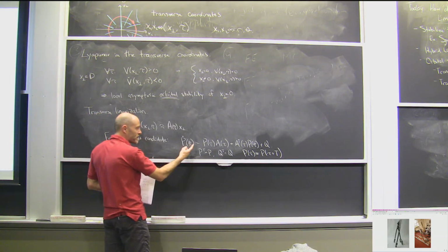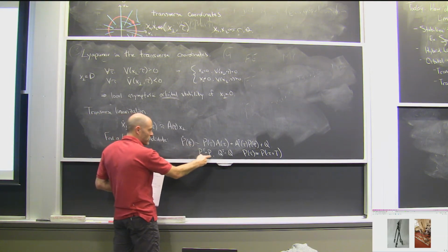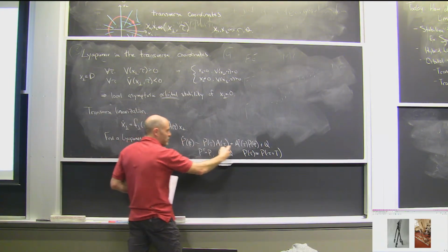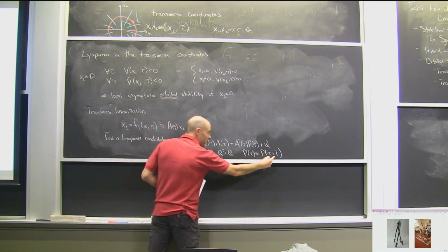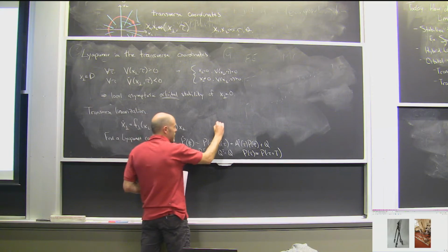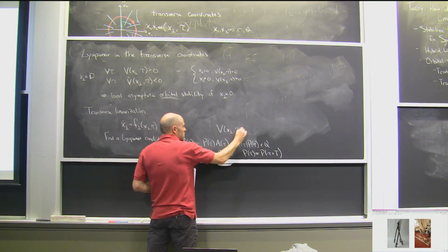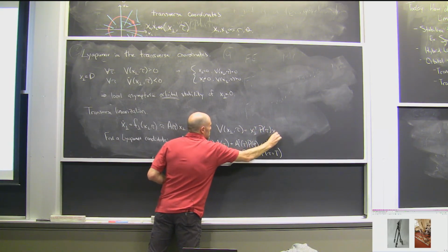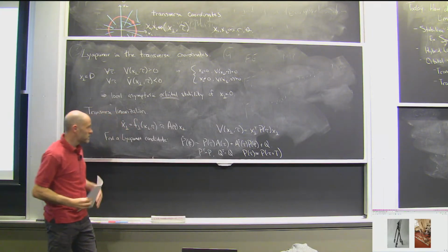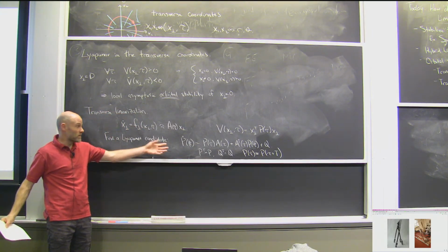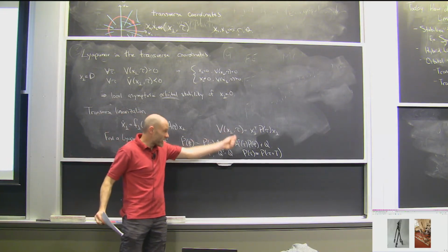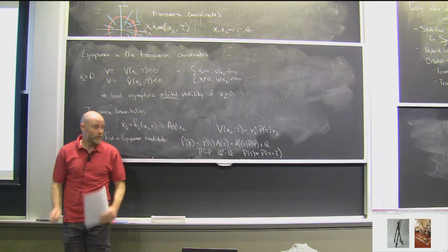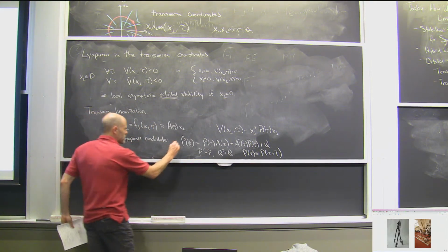So if I can find a symmetric positive definite matrix that's a solution to this Lyapunov differential equation, a periodic solution, then that gives me a Lyapunov candidate like this. That's a mechanistic way to come up with an initial quadratic Lyapunov candidate. Yes? Shouldn't this be negative P dot? Yep, thank you. I missed a negative on this side.